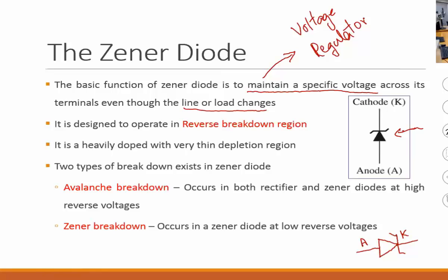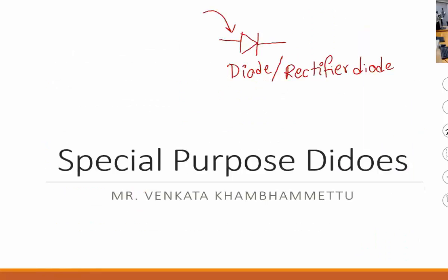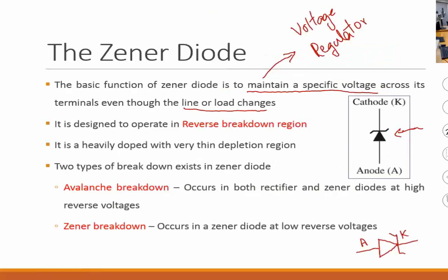Based upon what the model number of that Zener diode is, because every model number is different, especially for the Zener diode. They are not all the same. Unlike rectifier diodes, where all the rectifier diodes, irrespective of their model number, are exactly the same, for a Zener diode, changing the model number will completely alter the voltage value.